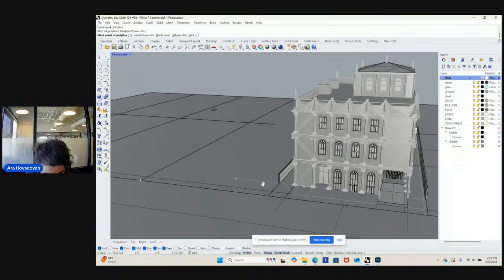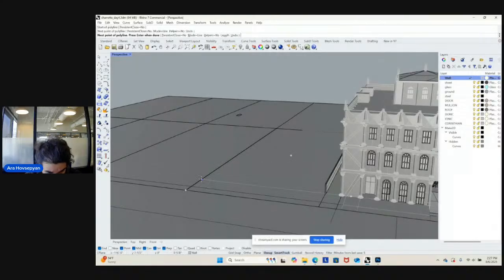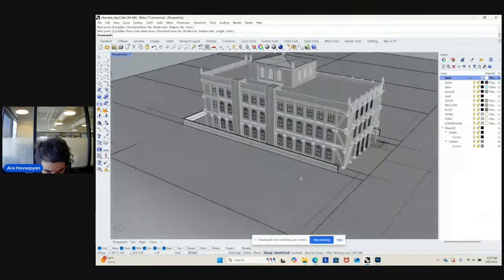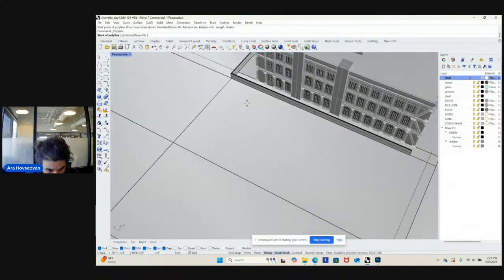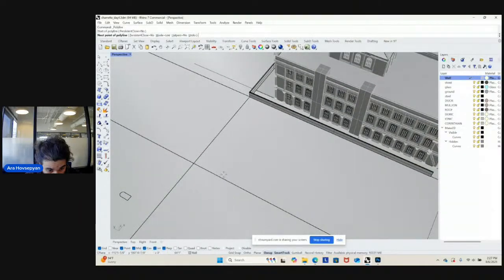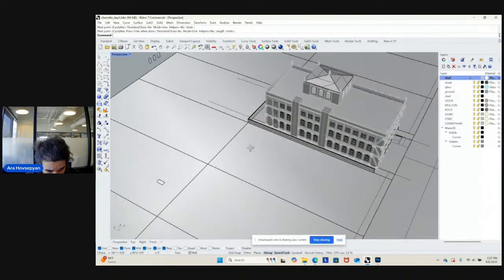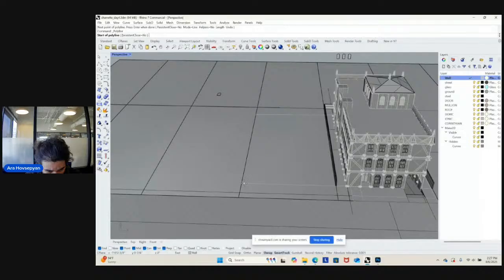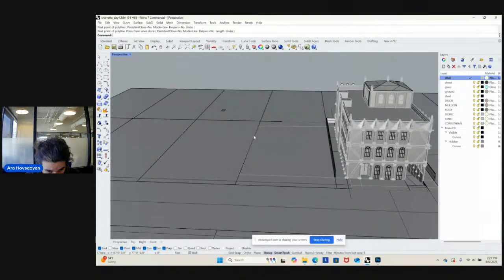Let's get this point. So we have here the 15-foot front setback, which also applies to the neighboring property. 15-foot rear setback. And then let's get our 6-foot side setbacks. A little bit over 6 feet. Bam.